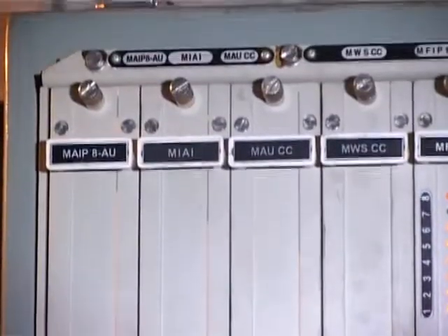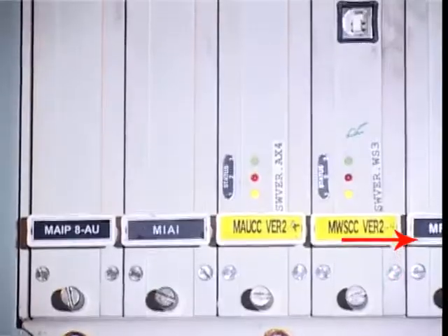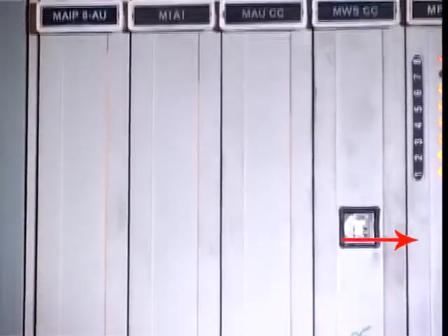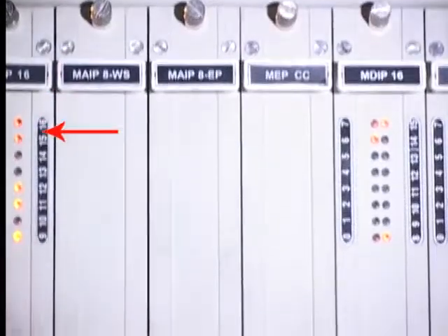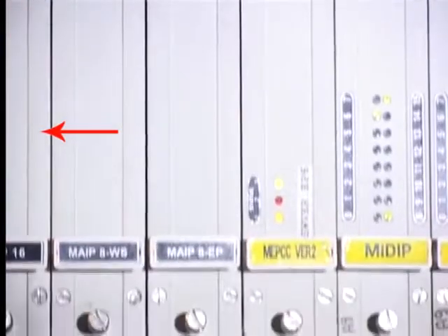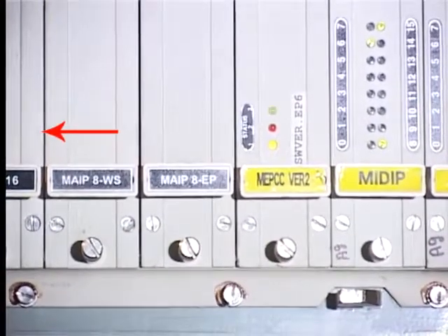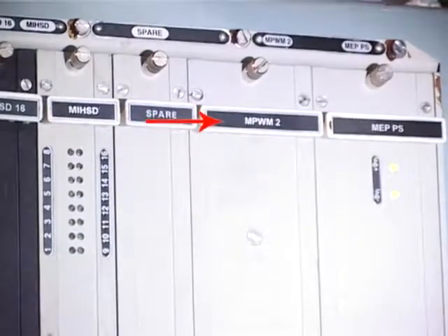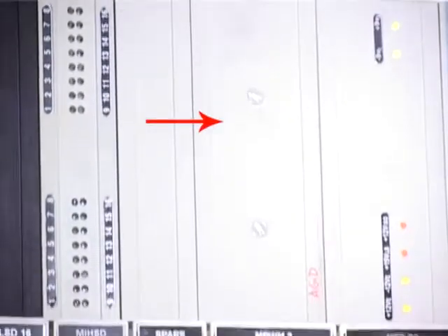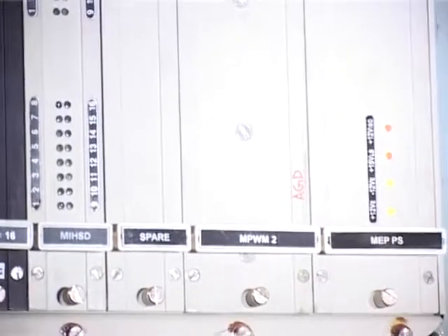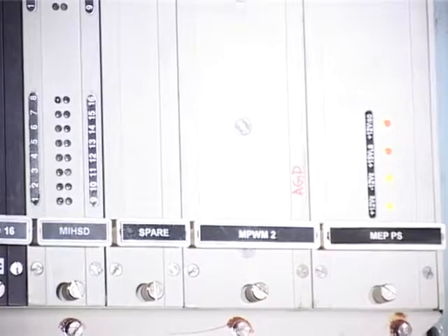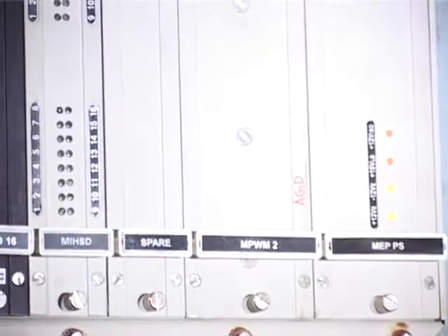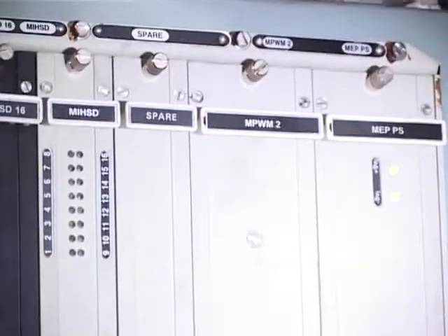BAP and LOP sensors. Frequency input card MFIP16. This card consists of the hardware required for converting the signals generated by speed sensors of traction motors and diesel engine. Pulse width modulator card MPWM2. The PWM card converts the low voltage pulse width modulated signals generated by the microcontroller system to a high power 72 volt output for controlling the exciter field current and auxiliary generator field current.